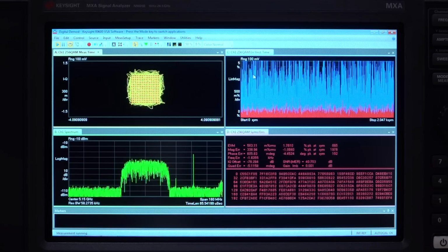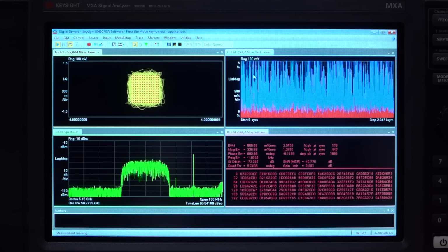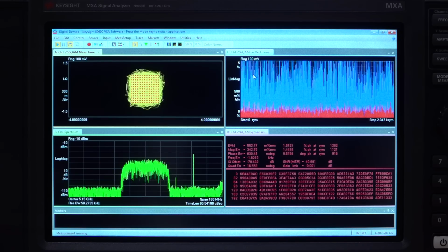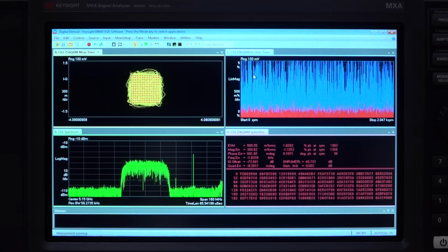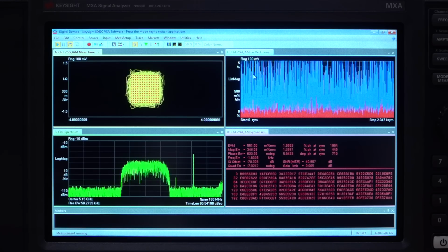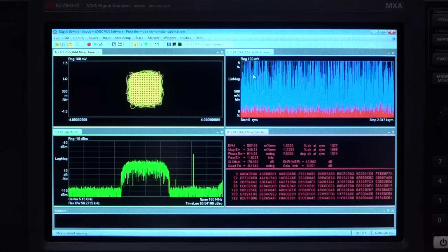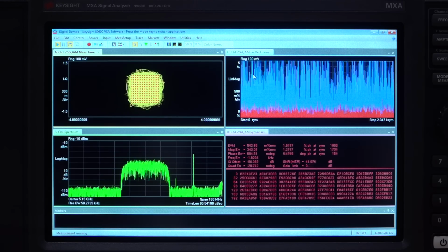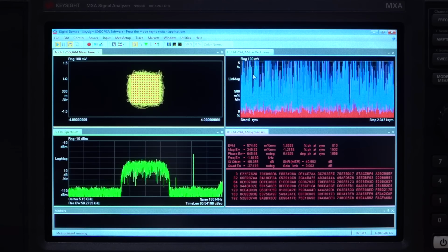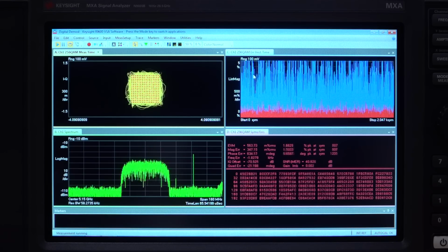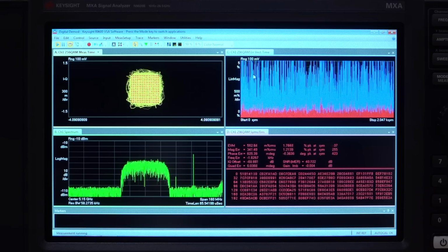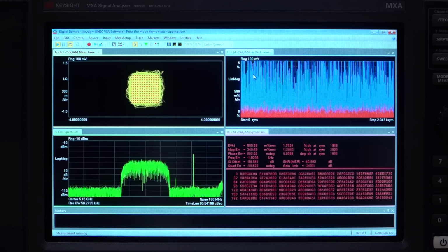So even though we cannot create a very broadband signal, as a first stage of a radio, this would be quite powerful, especially with the custom constellation capability of the EasyIQ software. And I hope that this highlights the benefit of a unit like this, even though you cannot create a broad spectrum 500 megahertz signal in arbitrary mode. Nonetheless, the carrier offset can give you a huge advantage in testing wireless systems. And there you have it.